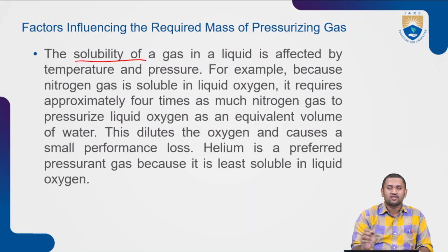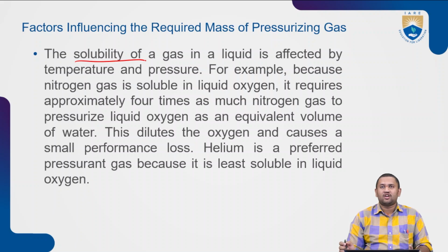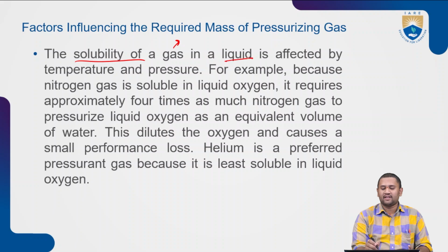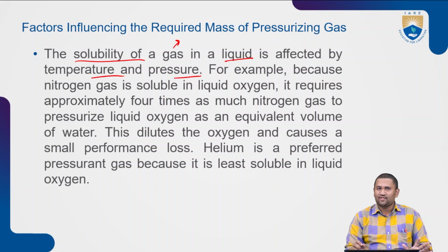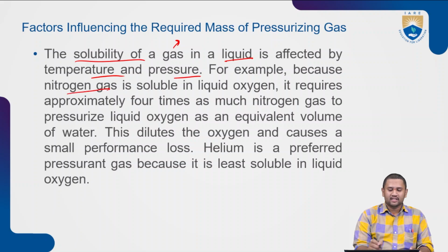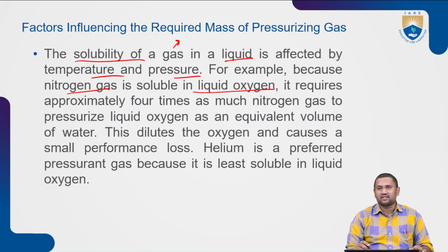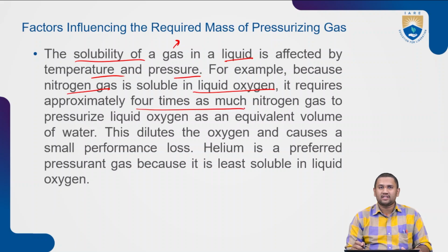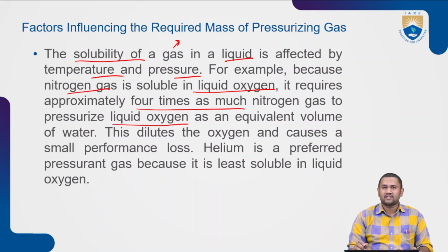Next one would be the solubility of the gas. The solubility of the gas, particularly the pressurizing gas in the liquid propellant, is affected by temperature as well as pressure. For a simple example, nitrogen gas is soluble in liquid oxygen, whereas it requires approximately 4 times as much nitrogen gas to pressurize the liquid oxygen as an equivalent volume of water.